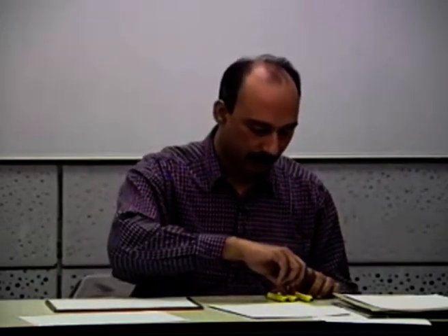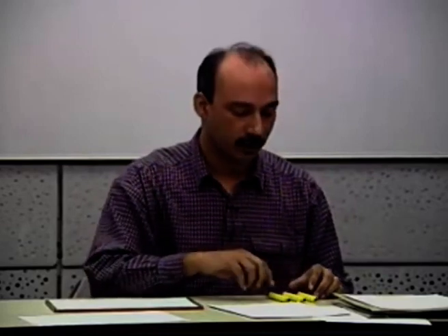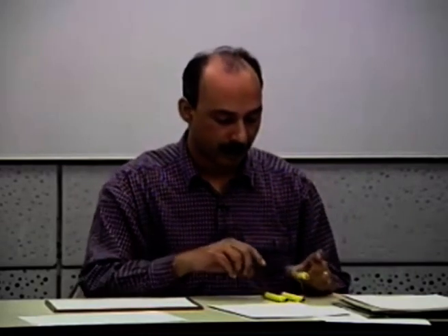If you can do that, then you'll be much safer, because there can be many situations where because of the increase or decrease in the elevation, you might find that the criticality of a particular point can vary. A point which you feel should be critical might not be critical because of the way the main line is laid on the field in actual practice. So the total dynamic head requirement must be calculated for each individual point on the main line,